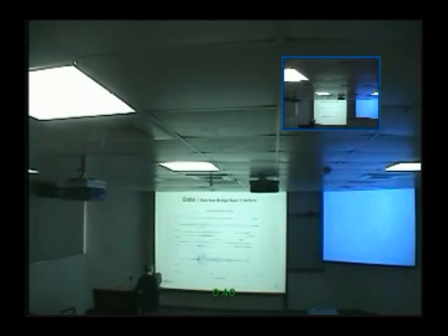Okay, so here the measurement that we made is not like modal analysis, where you have lots of sensors all over the bridge. What we put here is just one sensor at mid-span. We put a sensor at the center of the span, on the side of the bridge, not in the road center. And you let the trucks and cars pass by.